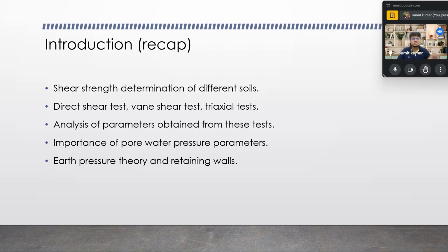A large box shear test is also there, and a normal shear test all of you have performed in your Bachelor of Technology in Civil Engineering coursework. There you came across the small 6 by 6 cm box in which the soil is prepared and then hammered.